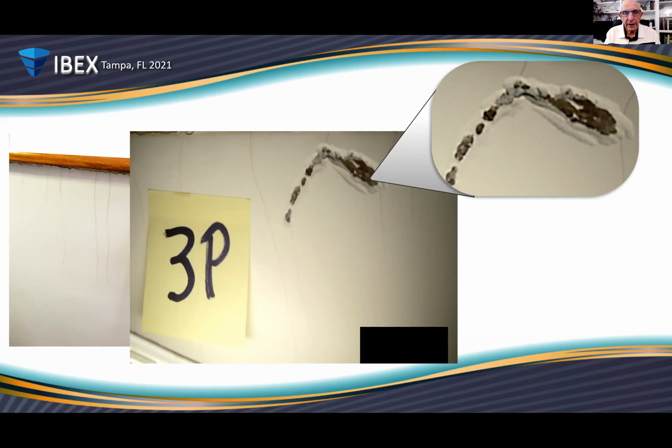Another place that's very common for thickness buildup is a fly bridge. Imagine taking that fly bridge, flipping it upside down and putting it in the mold. What you're looking at is this deep well down in the mold. It's like this wide, and it could be 24 inches deep, maybe even a little deeper on a bigger boat. And you have to get the gel coat down in the bottom of this well.